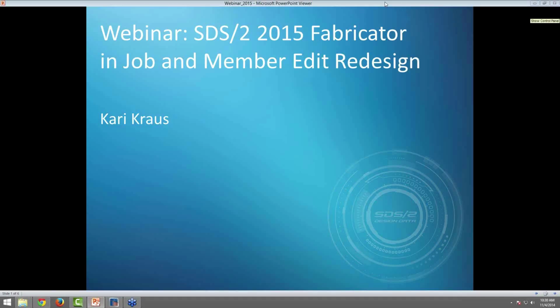Fabricator and Job. Why is the Fabricator now located inside of the job? The reason for the fab in the job is so there is one project file with the flexibility to change fabricators. Inside of the job folder, you can have multiple fabricators associated with the job to allow for the job to be switched between imperial and metric, or for different sequences to go to different fab shops and follow each fab shop standard.